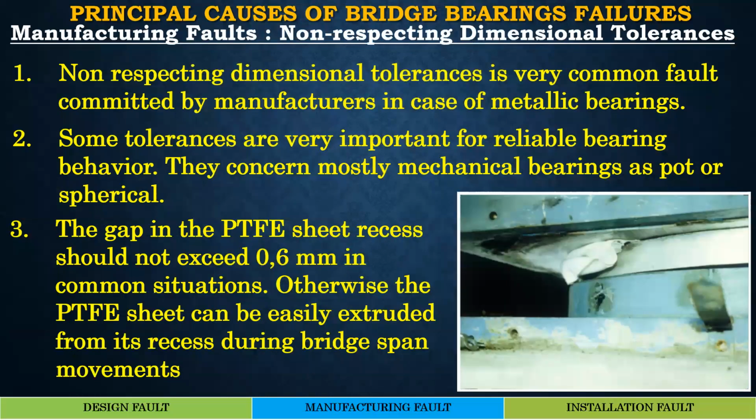Coming to the failure or non-respecting of dimensions and tolerances for metallic bearings, non-respecting dimensional tolerance is a common fault in the case of metallic bearings. Some tolerances are very important for reliable bearing behavior. They concern mostly the mechanical bearings. The gap in the PTFE sheet recess should not exceed 0.6 millimeter in common situations.